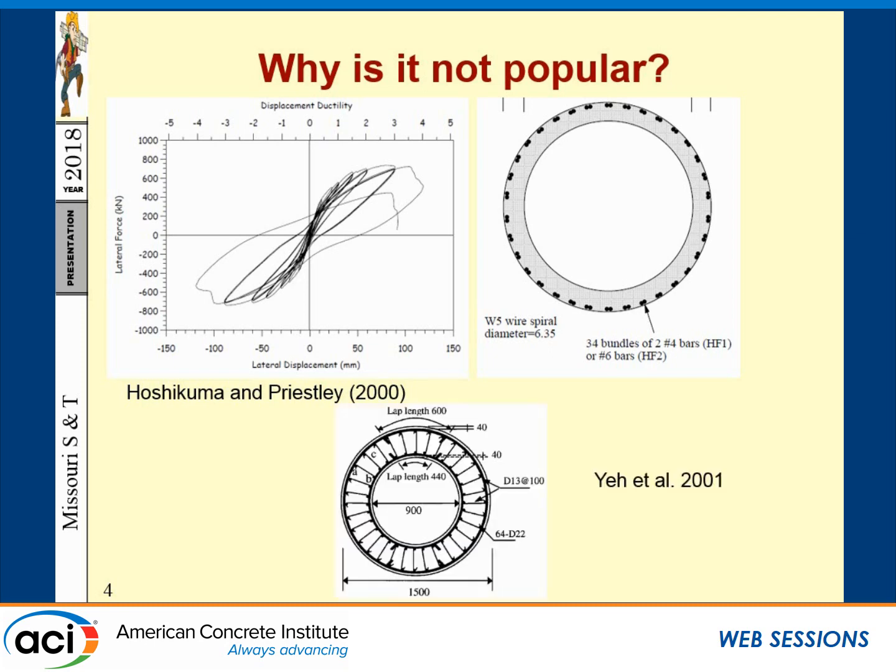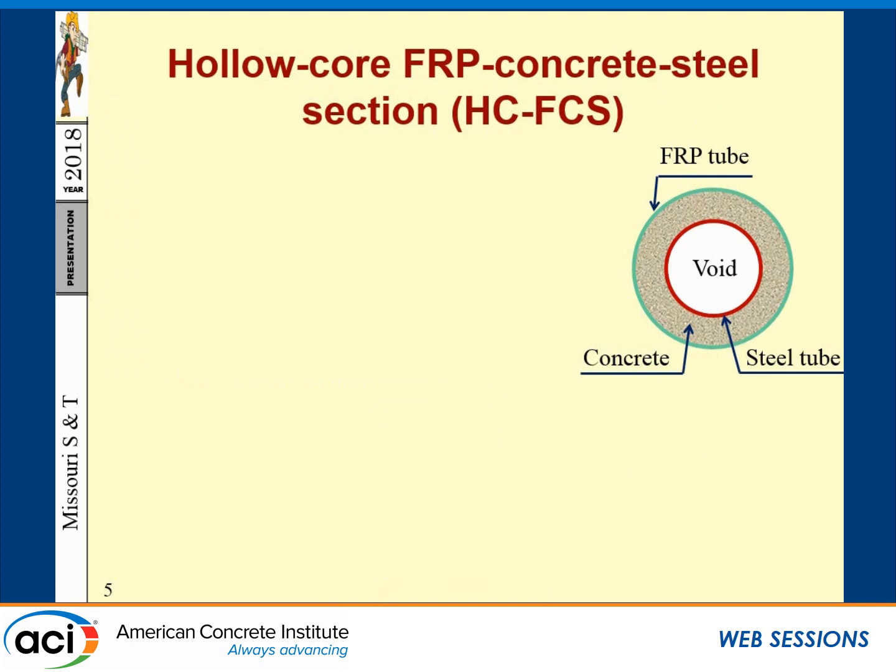Our colleagues in Korea came up with another solution where they used a double layer of vertical reinforcement and tied the layers together at each bar. You would expect this to improve the situation because now you don't have any unconfined concrete. However, looking at the cost required for workmanship, it's quite expensive. So we would not expect this scenario to survive in the U.S. market. So what did we come up with for hollow core columns?